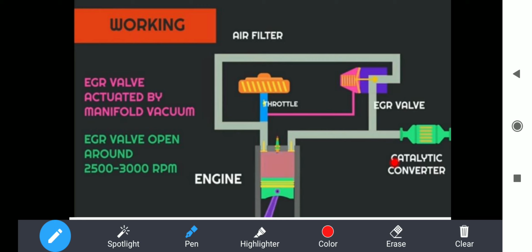And the second thing, the temperature of the engine increases. Because of the high temperature, with the engine running at high rpm, the fuel which is not burned inside the engine starts to evaporate into gases, as well as the burned fuel, and from the crankcase the oil is also heated and starts to release gases.